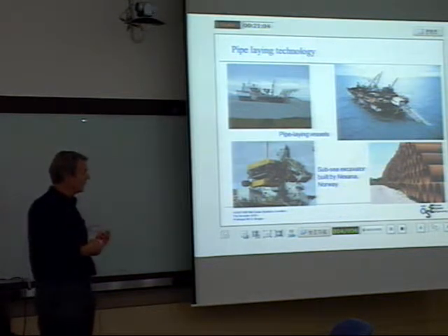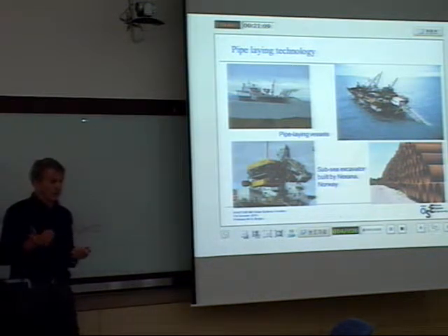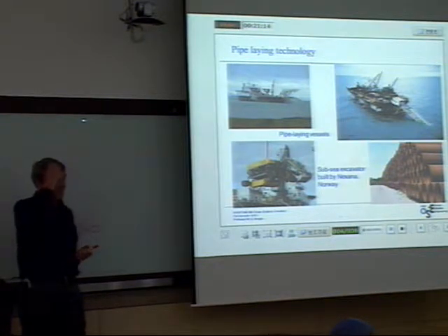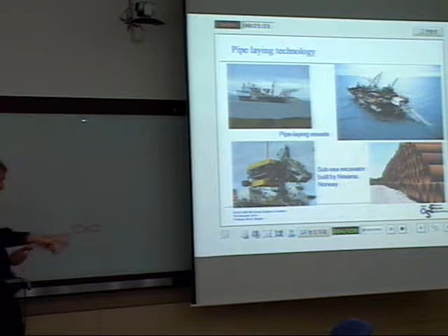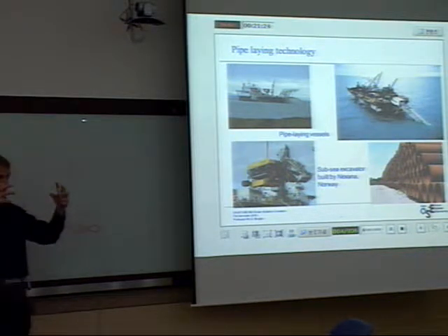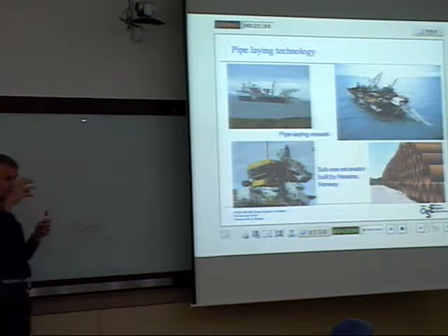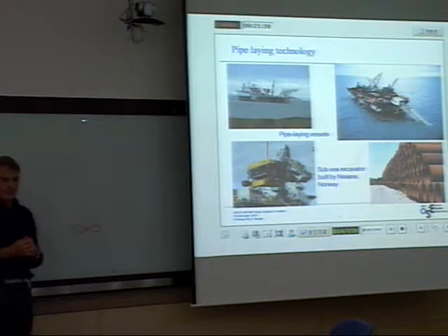But also you need to have monitoring, a checking of the condition of the pipeline all the time. And then there's something called a pig. Have you heard about this? A pig, it's not a pig like that, but it is a mechanical device that you send through the pipeline with the gas flow. And it can measure the thickness of the steel as it goes along on the inside and comes up on the other end.